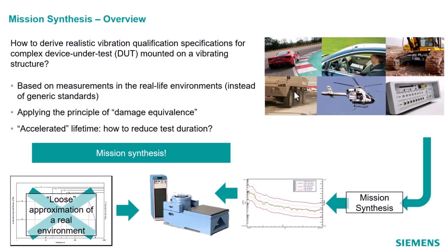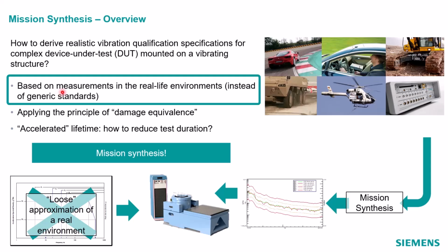So often the way that people will examine or test these articles is they'll use some sort of standardized PSD profile, and then they will shake that component on a shaker table using that standardized PSD profile. With the mission synthesis approach, we want to base that PSD profile on measurements taken in the real-life service environment of that component rather than using a generic standard.